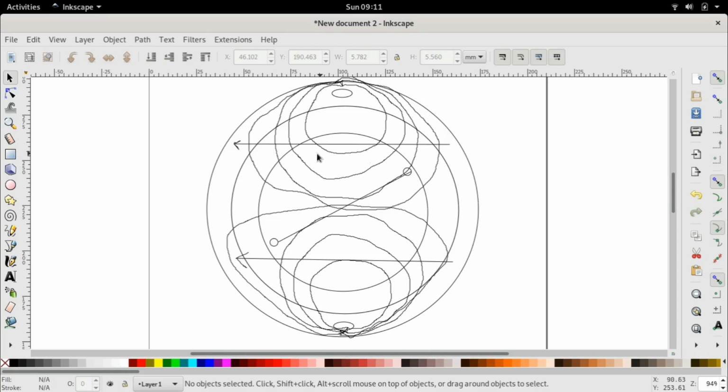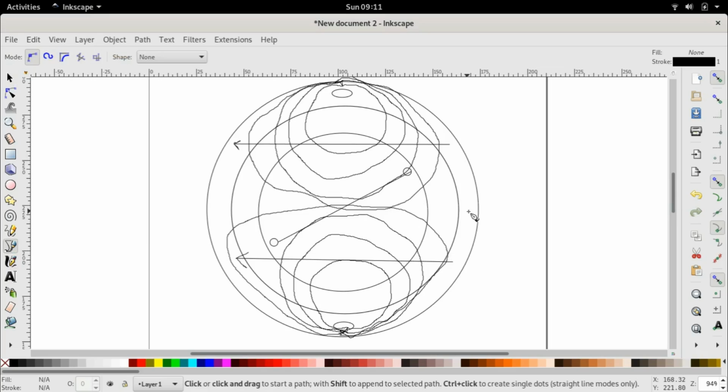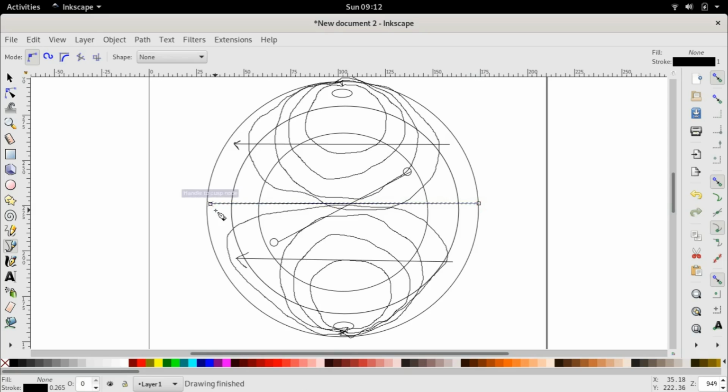But let us say that we have now considered that in these two halves, this is the net flux. With the net flux in both of these circles in the same direction, we can also now conclude that the total net flux produced by the stator will also be from the right to the left, right? This is something that we can conclude. So I could draw one single flux vector. I'm just going to try to figure out where the center is. Right, this is the center, and draw it from one end to the other end and put an arrow here as usual.